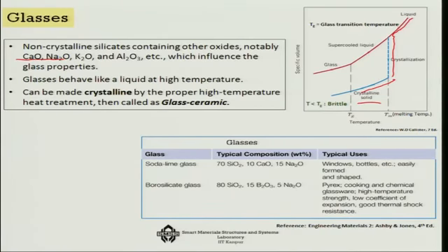But instead of holding it, if you cool it, the faster the better, you are simply freezing the fluid, the molecules' mobility is frozen, and that gives you the amorphous glassy structure. Beyond Tg, that glassy structure is very brittle, mostly because there will be a lot of micro cracks in that supercooled condition.